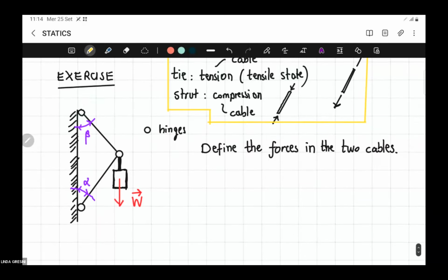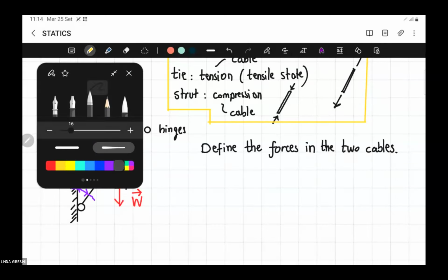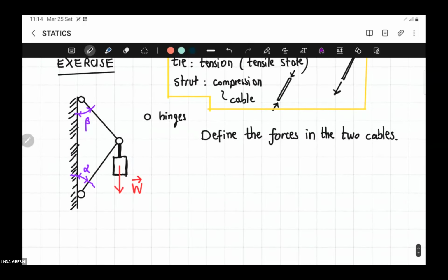So when I give you a hint, just resuming what are the steps when you have to solve a mechanical problem. The first step is to find a free body diagram. Okay. The second step is to solve the equilibrium conditions, which in this case are only two.